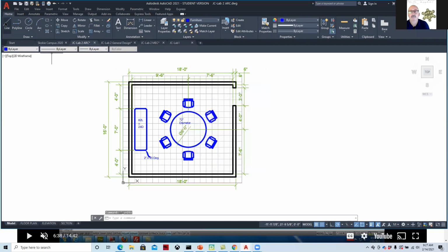So if I want to draw a 10-foot, 6-inch line, I can say from here, click. And then as I track this out, I can say, okay, at a 15-degree angle, draw this 10 feet, 6. You don't have to put the double quotes on; it just is the default. Enter. And then I can draw a line specifically at that length. That's how architectural units work versus decimal units. If I went through and got the mechanical, and this is a good segue for that, we're going to work with architectural units on this.